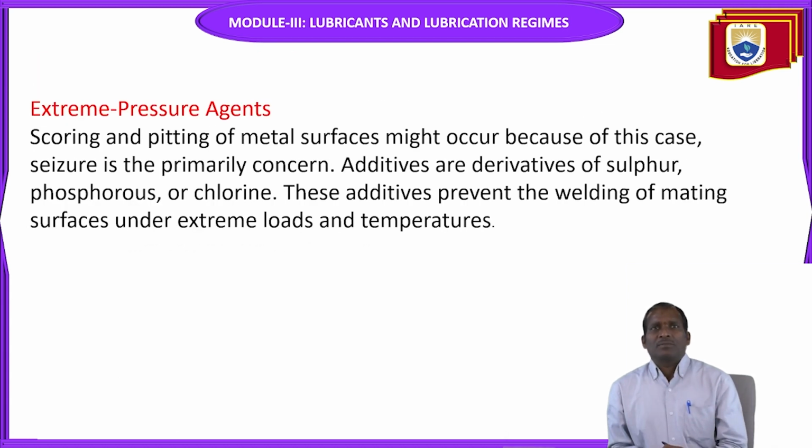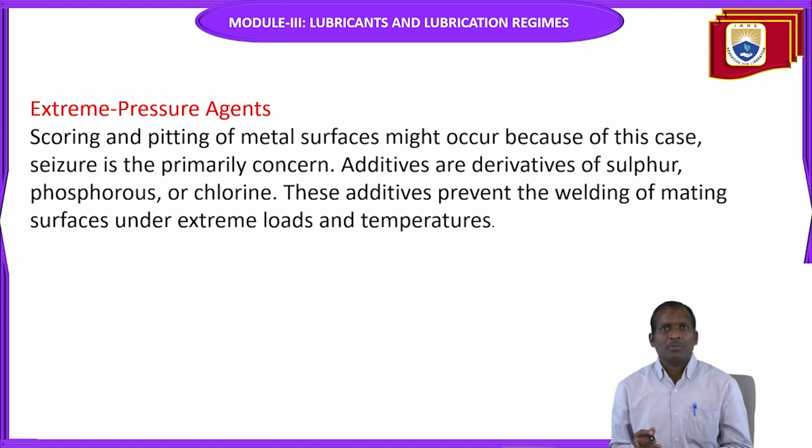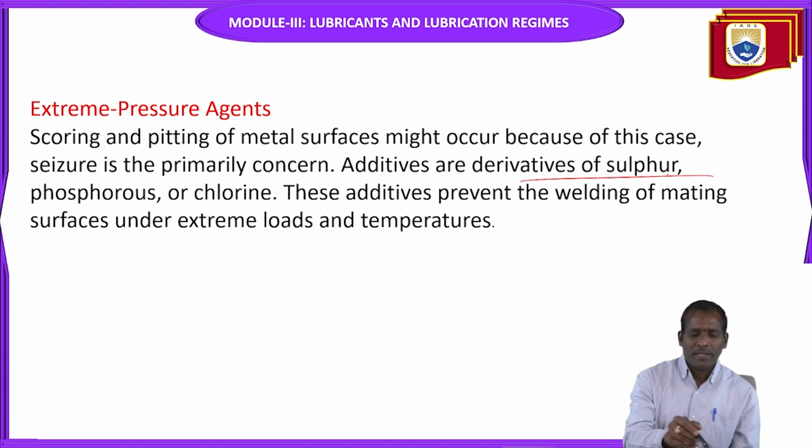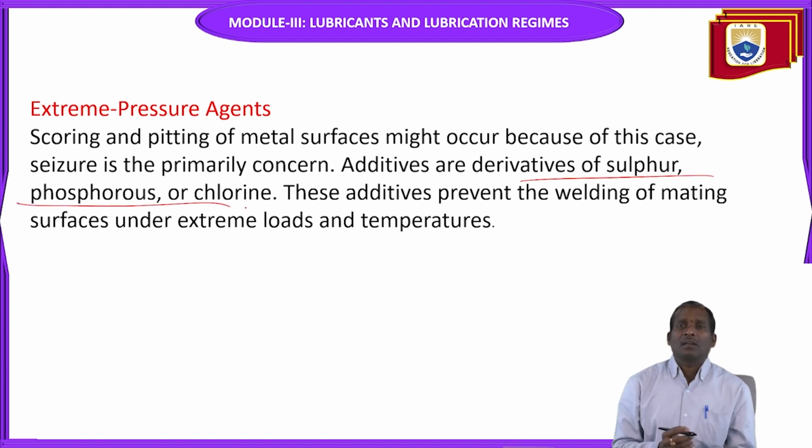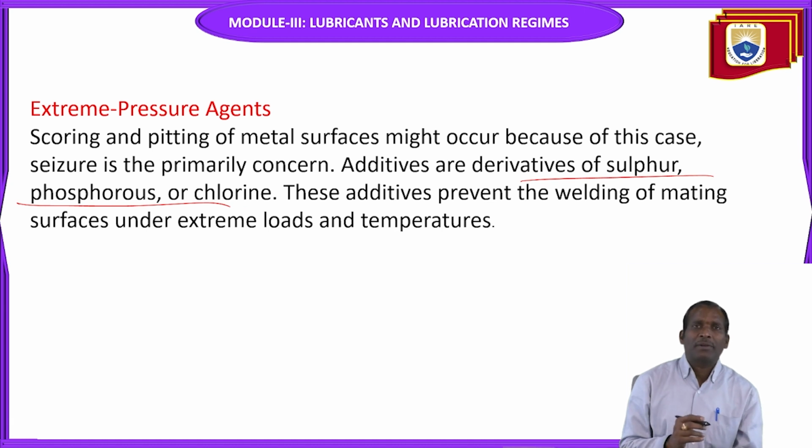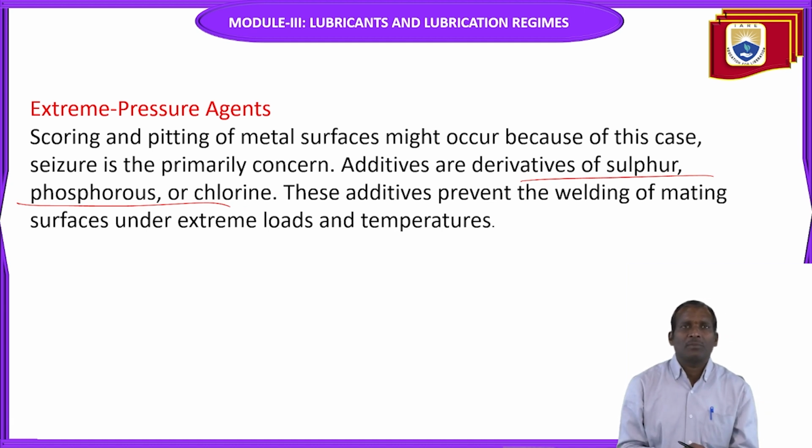Extreme pressure agents: scoring and pitting of the metal surfaces might occur. Because of this, seizure is the primary concern. The additives are derivatives of sulfur, phosphorus, or chlorine.